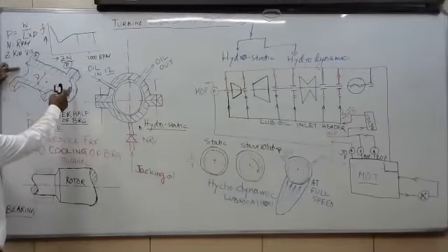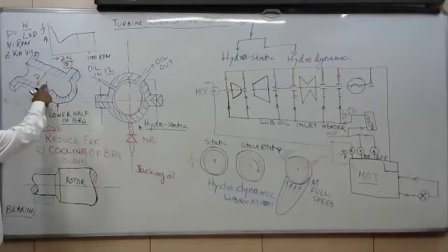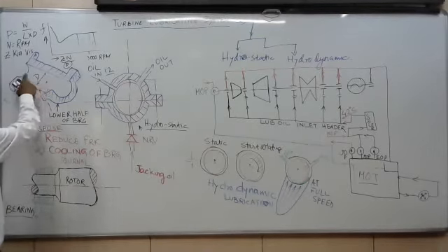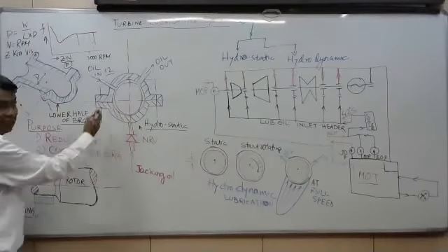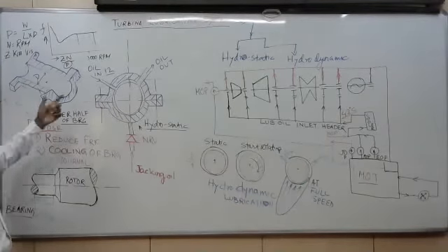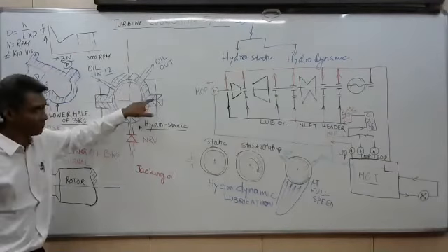You can see this is a sort of bearing surface. I am drawing the lower half. I have drawn it. The holes behind it may be 1, 2, 3 holes, or in a smaller bearing 1 hole, which will provide the jacking oil from the jacking oil pump below this. So this is the lower half of the bearing. This is the upper half of the bearing.